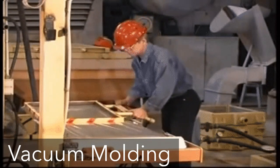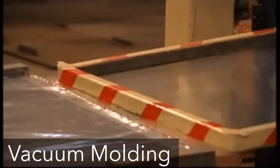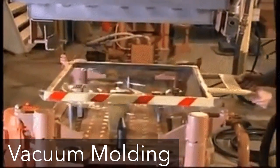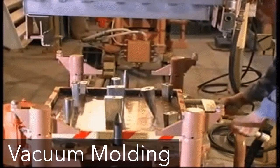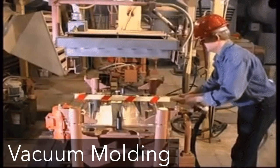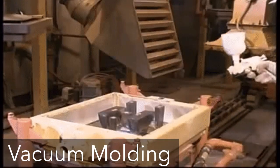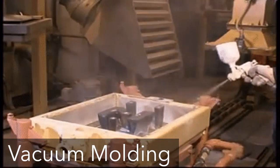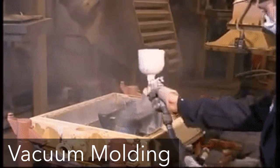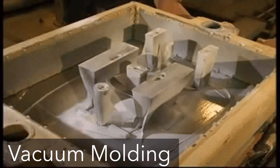Vacuum molding, also called the V process, was developed in Japan around 1970. It uses a sand mold held together by vacuum pressure rather than by chemical binders. Accordingly, the term vacuum refers to the making of the mold rather than the casting operation itself. Because no binders are used, the sand is readily recovered in vacuum molding. Also, the sand does not require the extensive mechanical reconditioning operation that is normally done when binders are used in the molding sand.